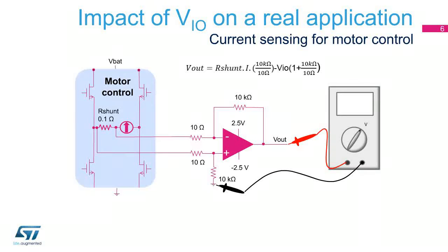In such applications, it is desirable to use a shunt with a very low resistance to minimize the series voltage drop. This wastes less power and allows the measurement of high currents without a significant voltage drop. A typical shunt might be 0.1 ohm. The lower the current, the lower the resulting voltage through the shunt resistor. So at high current, the VIO of the op-amp has little impact. For low current, it may become critical.